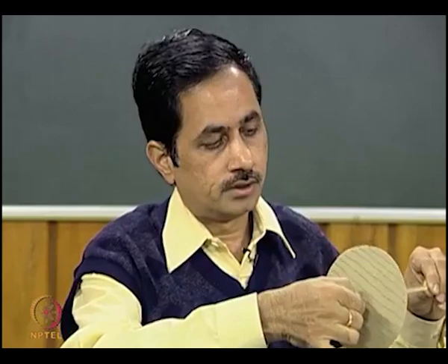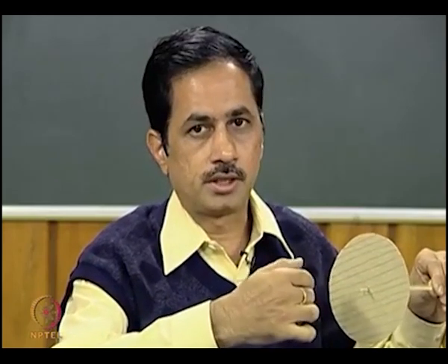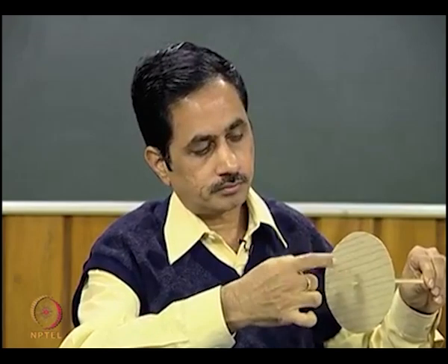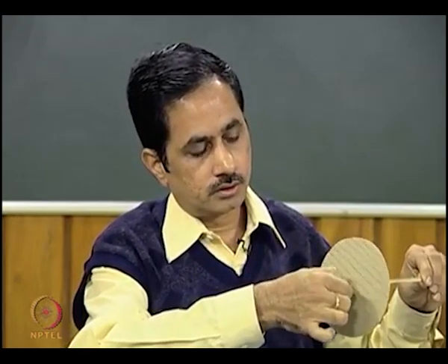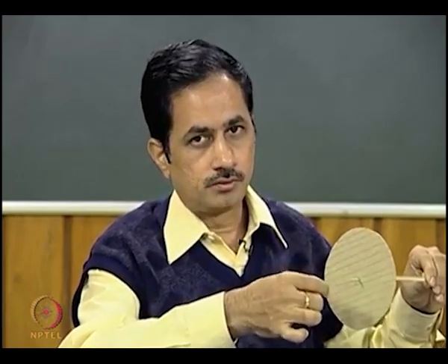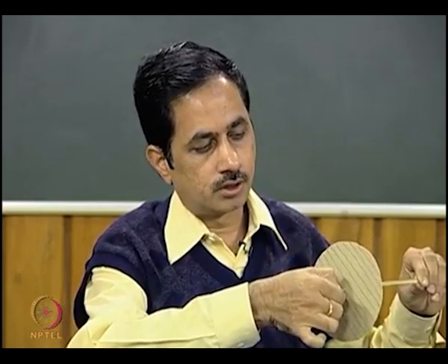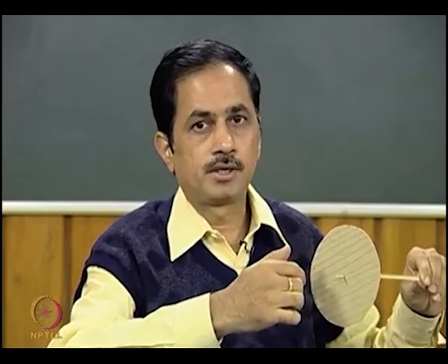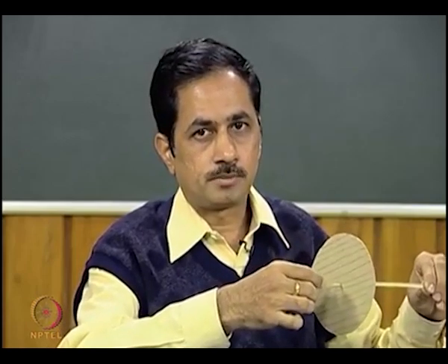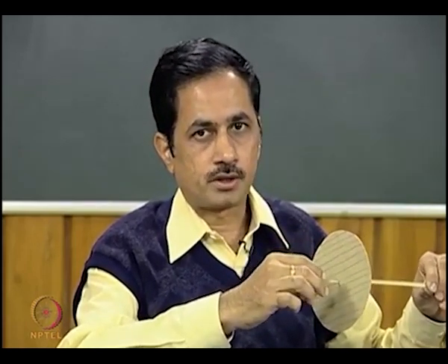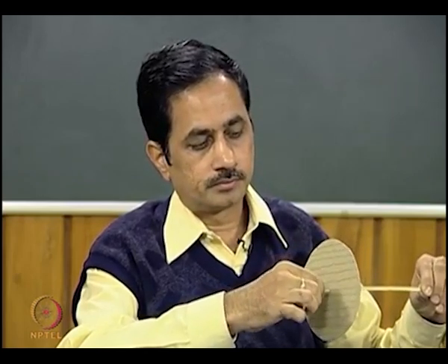Because this particular shaft is relatively rigid and a lot of damping is there, the oscillations are only one or two, but if the damping is less, which is the case in most practical situations, we can have large, continuous oscillation.